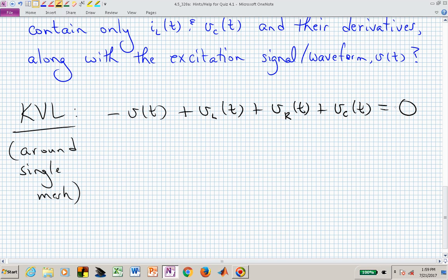And that brings us back to where we started. The algebraic sum then of those voltage drops or rises, however you want to think about it, but it's the algebraic sum. We need to keep track of the signs that we've identified with those particular elements is now given by this equation. And this could be a true equation.